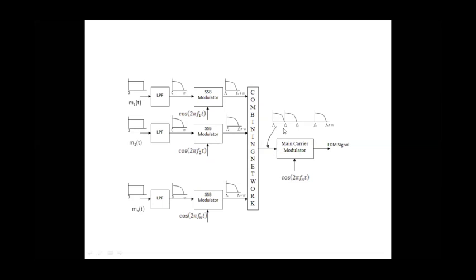after combining them, you'll get a signal like this. This signal is called a frequency division multiplexed signal. You see, here all are actually multiplexed. They are placed side by side in different bands. So a given band from F1 to Fn plus W is divided among n number of message signals. So this is called simply a frequency division multiplexed signal.